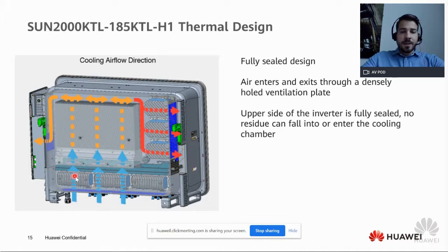This fan is removable. It can be exchanged or replaced if anything happens. But it is certified, and designed to reach the operation life cycle of the inverter, so there is no regular maintenance needed on the fan. One of the design concepts is that on the upper side of the inverter there is no hole, so nothing can fall inside the inverter's cooling chamber.